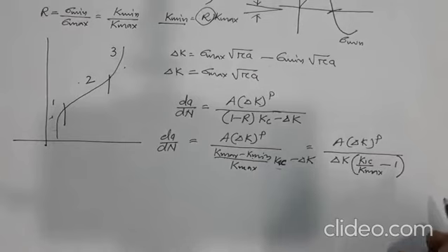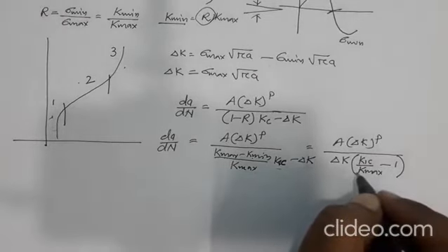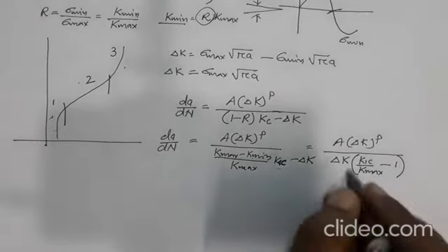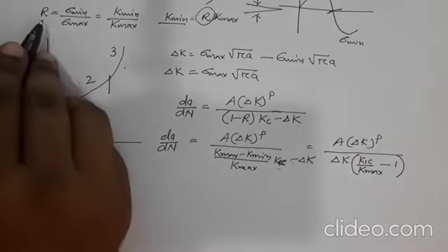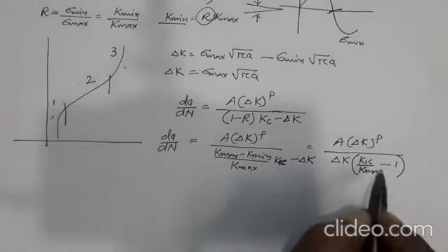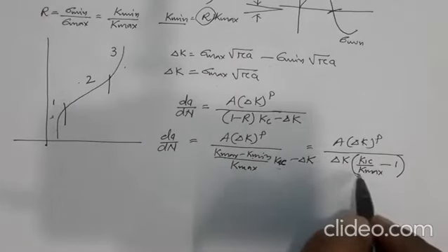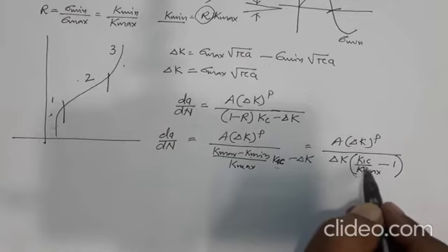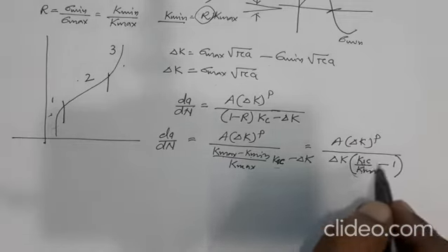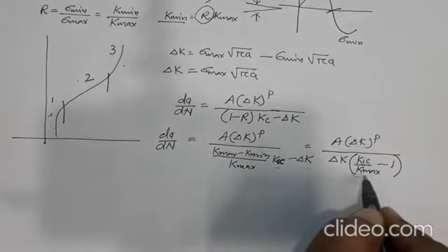okay. And now, what is happening here is also very clear. The effect of R actually is reciprocated in this way, and what we are seeing here is that this factor defines how much your K max is in comparison to the fracture toughness of the material, okay. So we can further break it, so this will be K1C minus K max divided by K max.